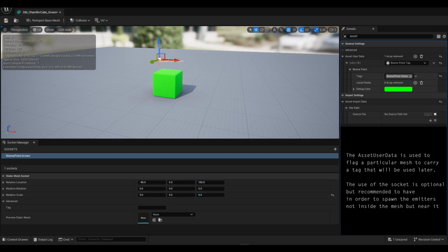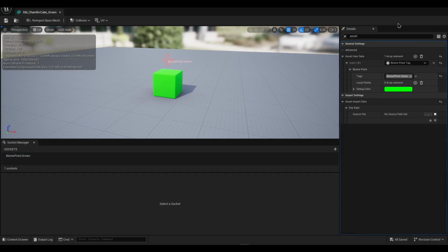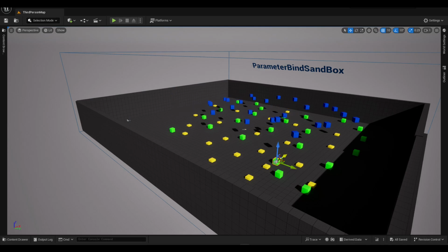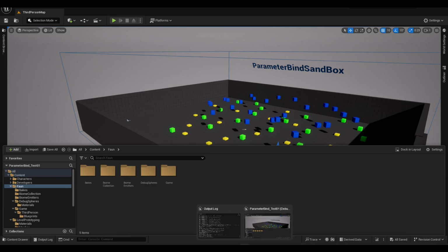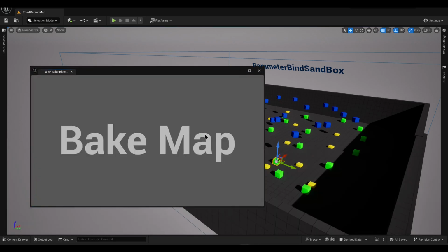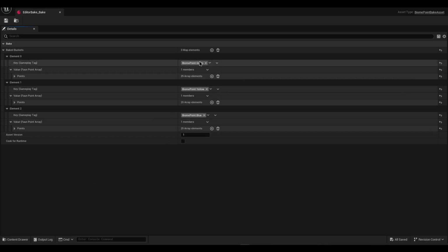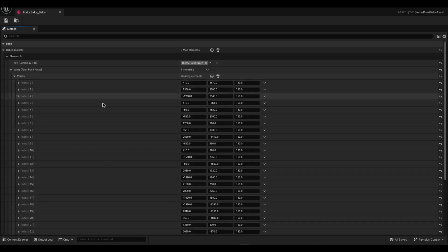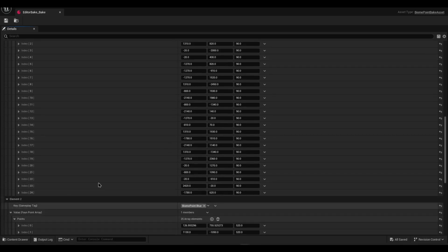The biome point tag is a lean atomic component that, as asset user data, can be inserted into static meshes and allows the mesh's position to be recorded within a hash grid. Once saved within the mesh and positioned in the level, the hashmap bake command saves the hash grid to an overwritable and editable data asset. The runtime subsystem manages instance queries with a loose octree method, eliminating the cost of full scene search.